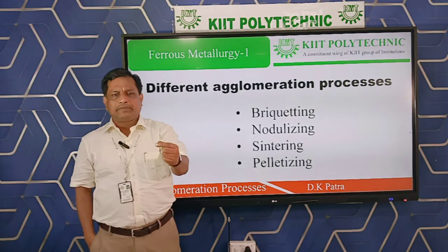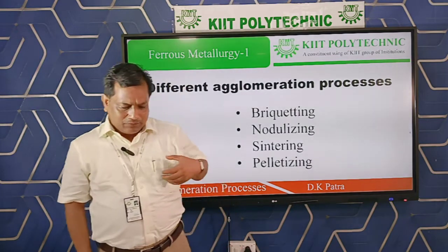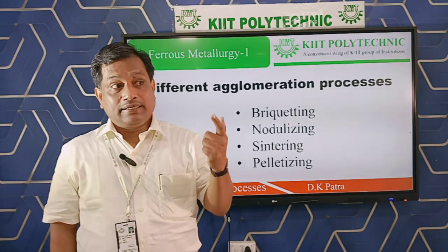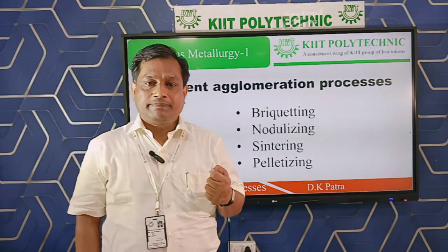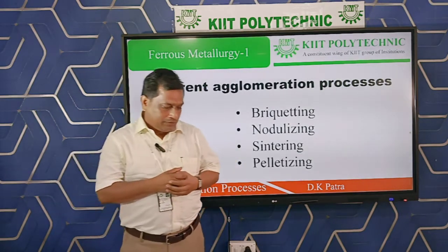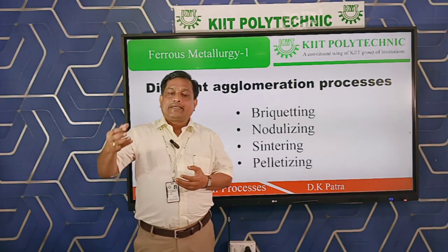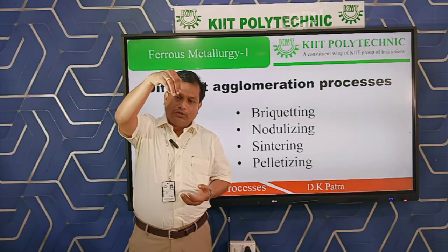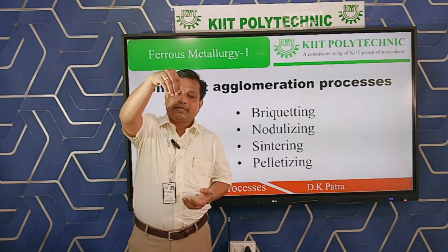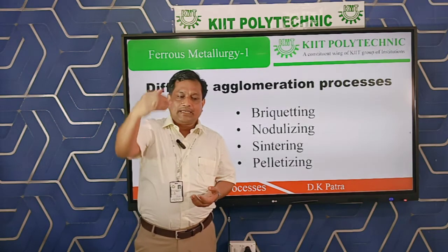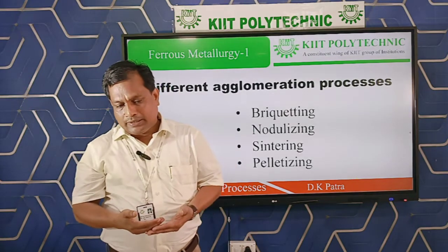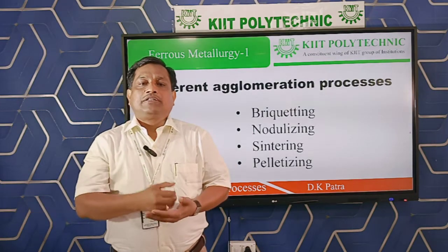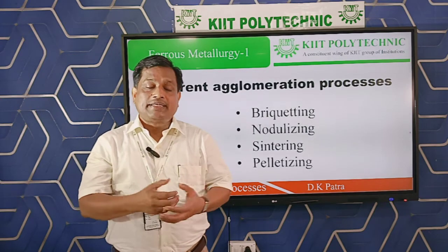This is the highest, biggest furnace that we deal with as metallurgists. We put the iron ore in from the top of the furnace, and generally from 8 to 10 meters from the bottom, we are supplying carbon monoxide, or creating the carbon monoxide inside the furnace.